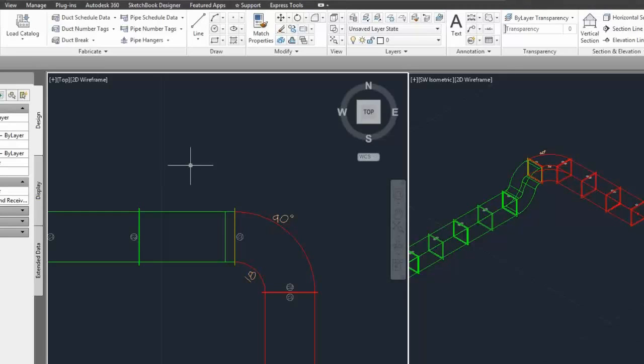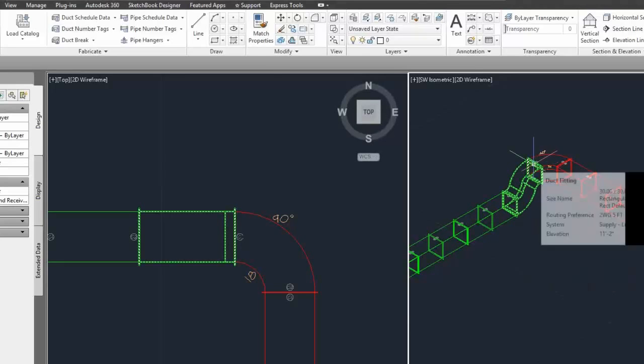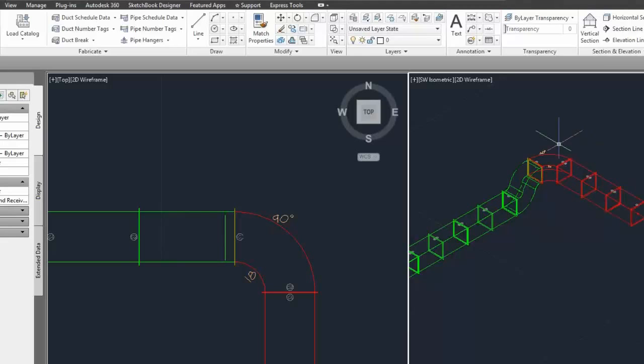And the property set that we are looking at, which is the bottom of that offset tag, refers back to connector 1 of the fitting, and connector 1, which is here, is okay. Its elevation is correct. It's the connector 2 elevation and all subsequent duct that is incorrect.